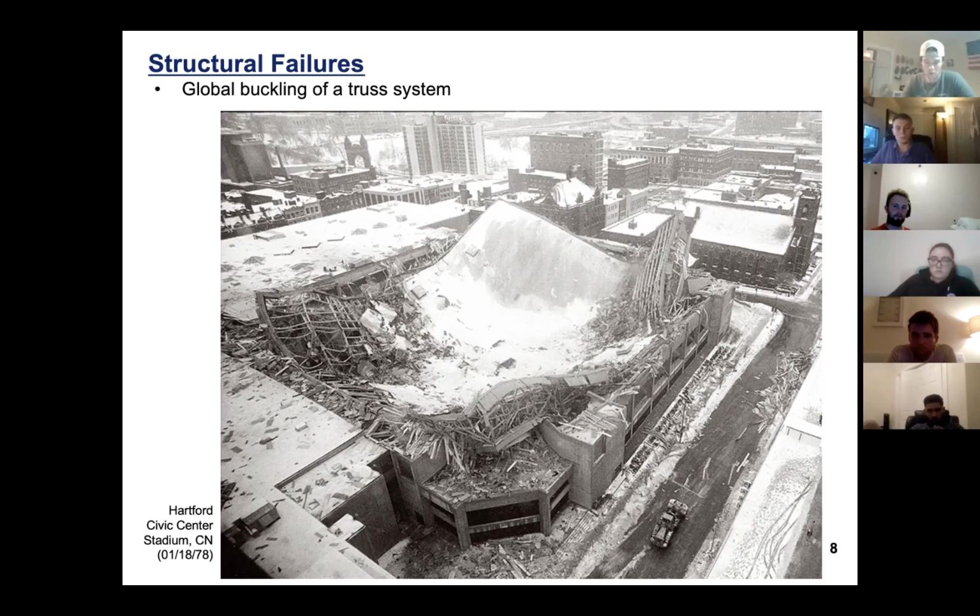In other words, sudden failures of structures are an absolute no-no in our business. We absolutely do not want structures to fail all of a sudden. You would rather see that before failure, the structure system will exhibit some large and, most importantly, measurable deflection. And we will use it as a sign to provide structural repair or even to evacuate the structure just to protect human lives.